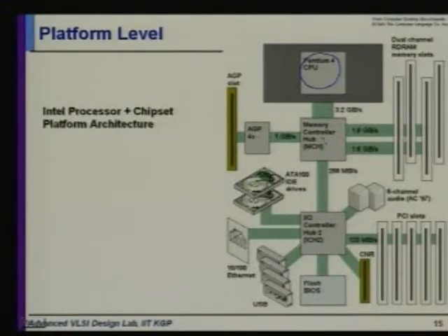So if you open it up, then you will see these other chips. Okay, so this is a Pentium. So this is a memory controller hub. Now the processor typically communicates with the memory using a very high speed bus, and the other IO devices, etc., they are not linked into that bus because they do not have that speed.